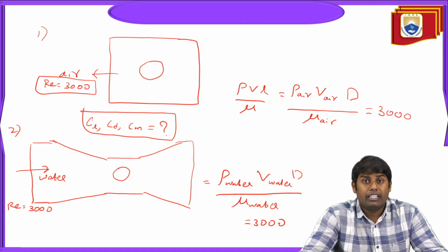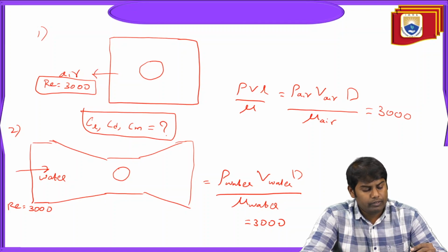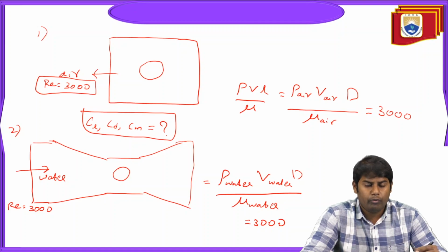So what do we conclude here? When you have the same Reynolds number, the values of Cl, Cd, Cm will not vary whether you do it with experimental water or with air. It doesn't matter, the results will be the same. This need not be only with numerical. If you do the same for experimental, and change between air and water, say the numerical as water and the experimental as air, you should not think that the results will change.